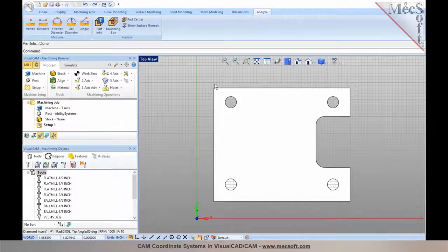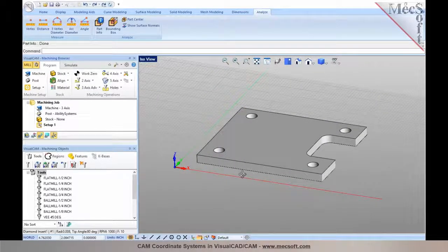The orientation is the orientation in which the part needs to be placed so that it is suitable for machining. In this particular case, you'll notice that the length of the part is parallel to the x-axis, which means the longer side of the part is along the x-axis and the shorter side is about the y-axis. If the machine tool that you're working with has more travel on the x-axis as compared to y, then the way we currently have this part oriented looks right. So we don't need to rotate or do any additional transformations.